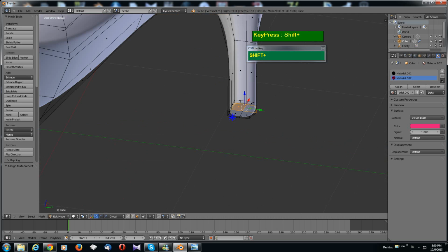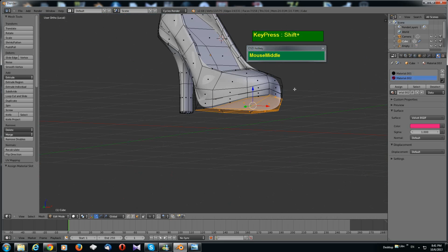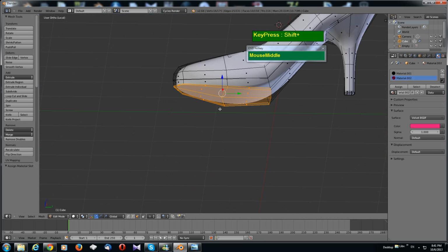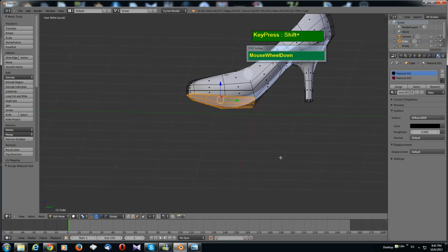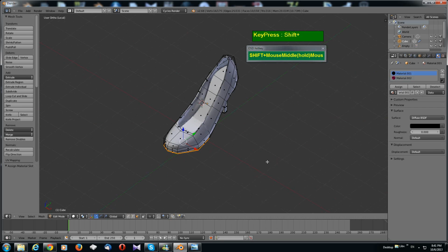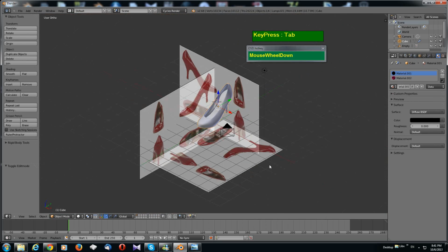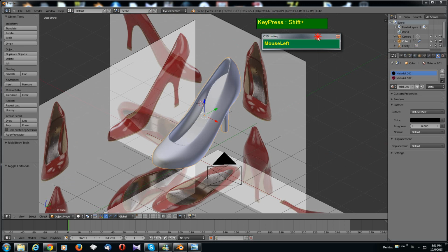And then since now I've got 2 materials, I'm going to reassign the black material to these faces. Now when you're working with Cycles materials, you can only see the effect once you hit render. So I'm going to select these faces here again and assign them. Now I'm going to press forward slash on my numpad to go back to unisolated mode. I'm going to do a test render.